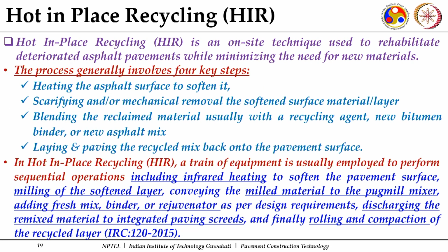Now the other common recycling technique is hot in place recycling, or we can say on-site recycling, and this is again to rehabilitate deteriorated asphalt pavements while minimizing the need for new materials. Here, specifically when we are targeting surface layers which can be easily modified, where the distresses are restricted to the surface layers, hot in place recycling is quite popular.